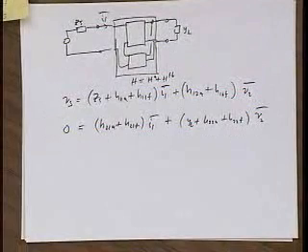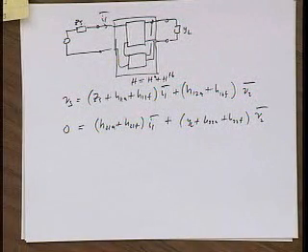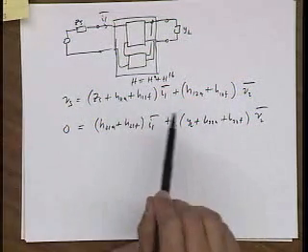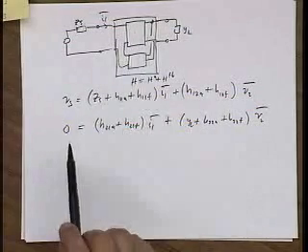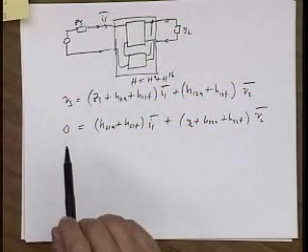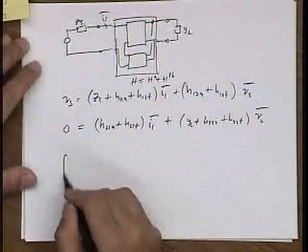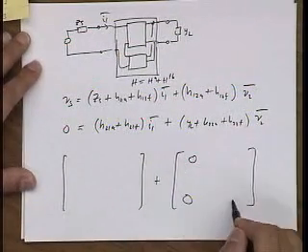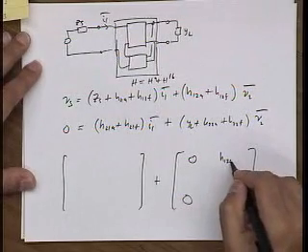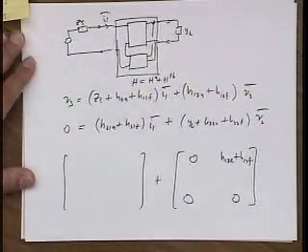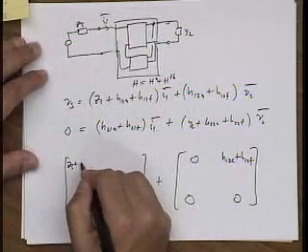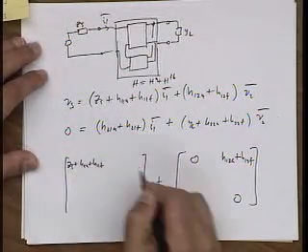But what I'm going to do now is very simple. I'm going to say, wait a minute, I can now pretend that instead of summing the actual matrices, I had summed two different matrices. And the two matrices look like this. 0, 0, 0, H12 amplifier plus H12 feedback. Over here, I'll take the full term. I'll take ZS plus H11A plus H11F.